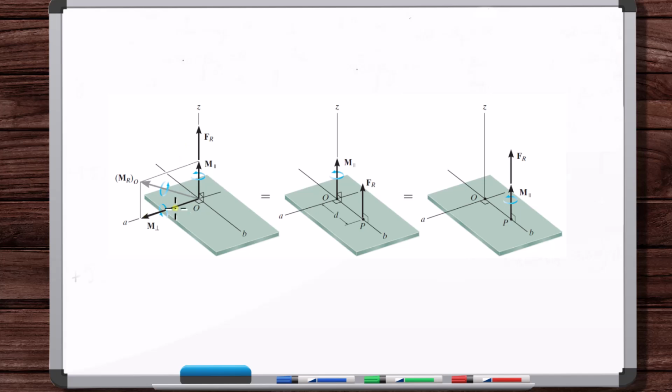You get the same result, this perpendicular couple moment and force, but the way you analyze those systems is a little bit different. But once you have that perpendicular couple moment, you just move the force perpendicular to the couple moment axis, and then you're able to remove that perpendicular couple moment and just have the force. But it's not as simple in general when the couple moment is not perpendicular to the force axis. So again, we worked examples where we just stopped once we found the couple moment and the force at the point. But you can go further.